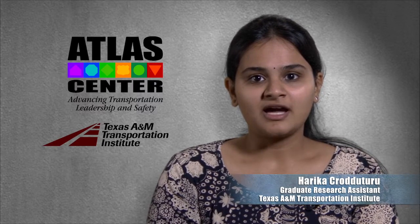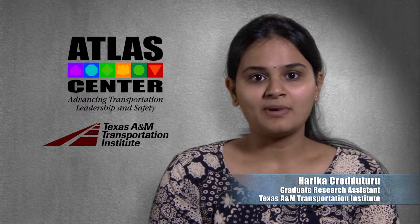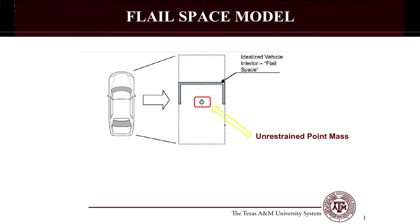Michie introduced the flight space concept back in 1981 in an attempt to better define occupant risk criteria for evaluation of roadside safety devices. The flight space model assumes the occupant is an unrestrained point mass, which in case of an impact acts as a free missile inside the occupant compartment.